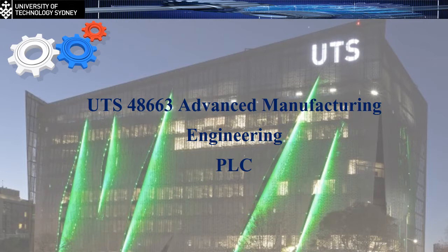That's number 1. The other common error was finding the value of the cost of the tool. So just remember, once again, we have to look carefully at the equation for the cutting tool cost. We have to find first the number of edges we are going to use for the cutting tool. Just remember, it is going to be the number of times we can grind the cutting tool plus the original edge we have. So if we buy the cutting tool with one sharp edge and we can grind it 6 times, that means the useful edges is going to be 7.